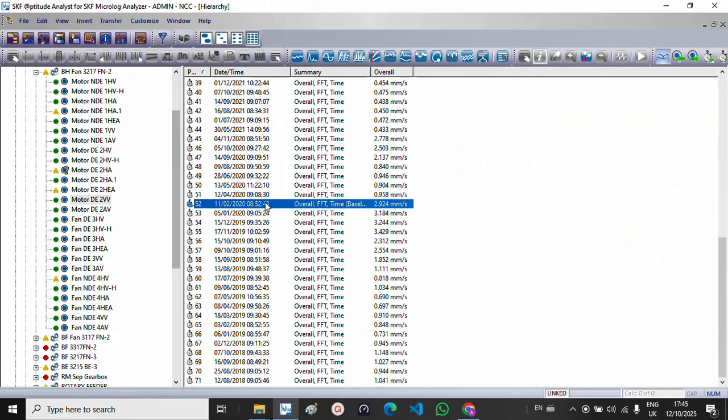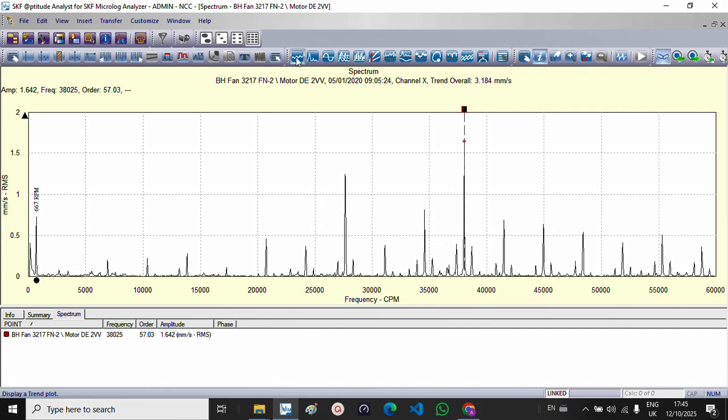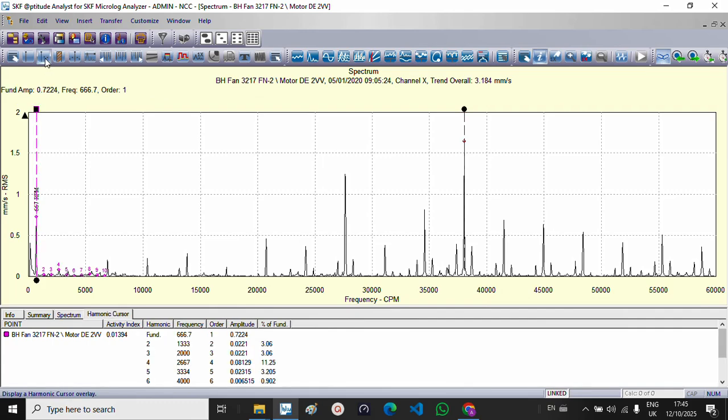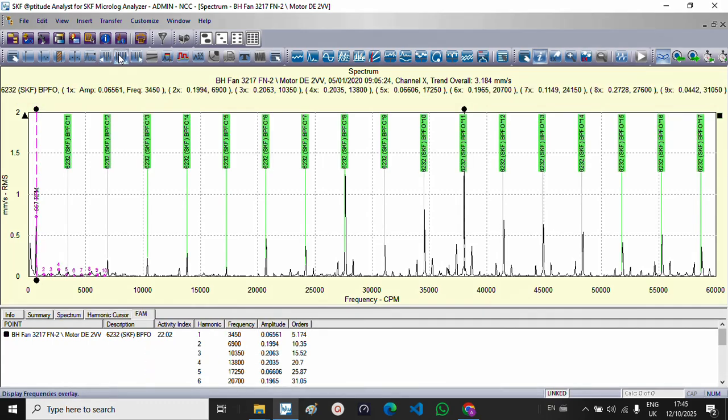Vibration analysis is not easy this way. This is the search for the problem or the faults in the bearings. Therefore, we see the 1x frequency, check the harmonics, check the bearing frequencies, and see if there are high frequencies related to the bars in the motor. We check all the frequencies, the forcing frequencies related to the component and the equipment.